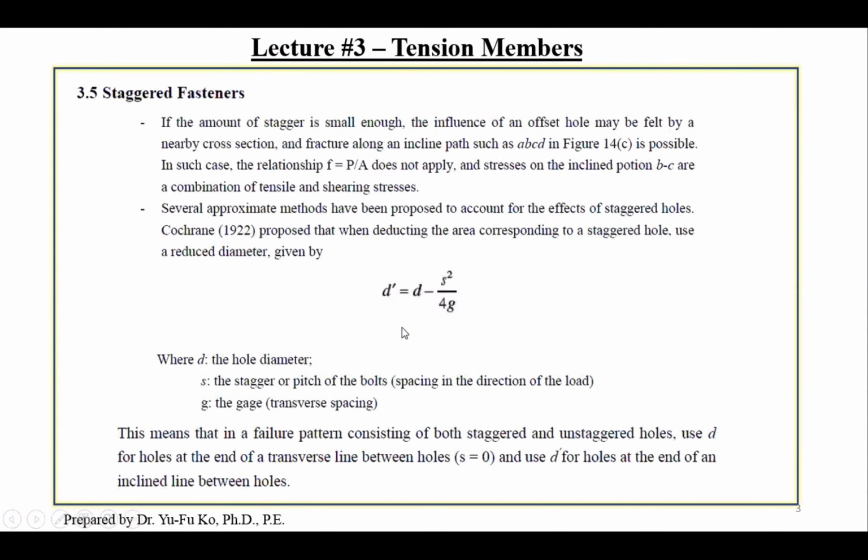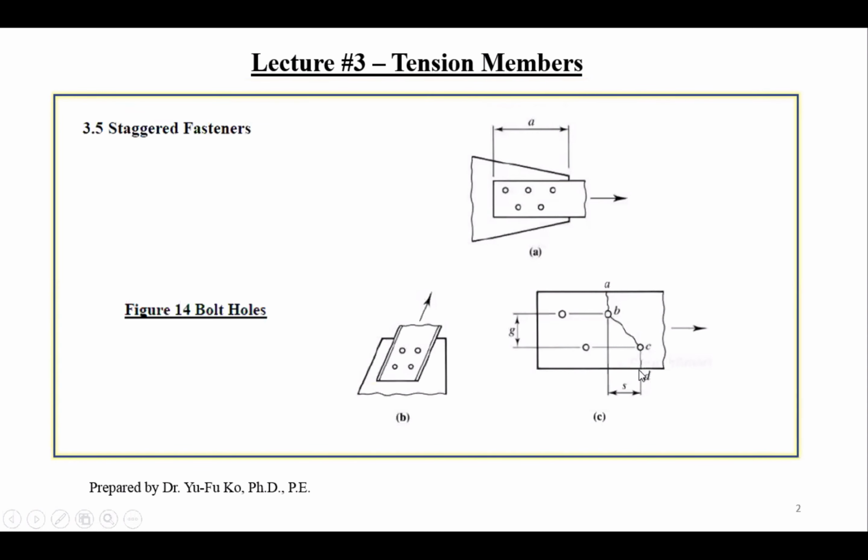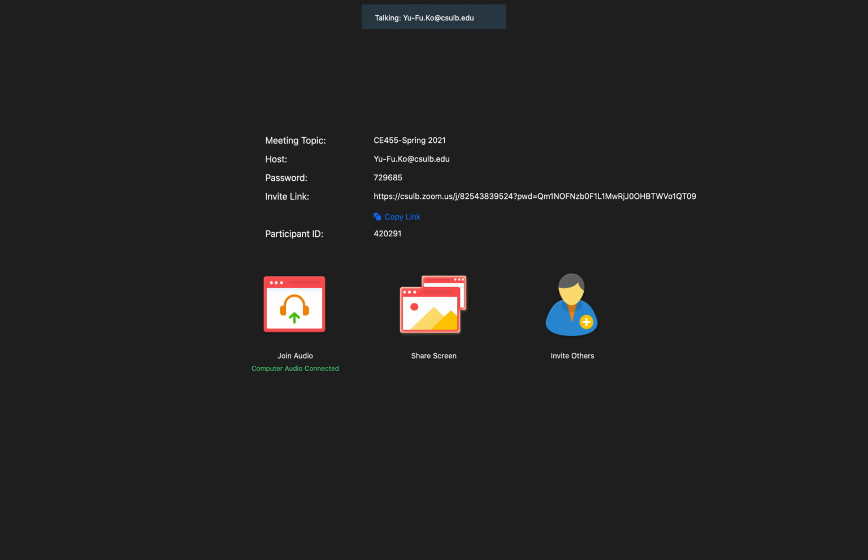Okay. Locally, maybe you see the A net locally maybe stronger, bigger, because the hole value is smaller, right? So maybe you are thinking A net is bigger, but you've got to look at the overall failure path to determine whether it's actually stronger or not, not locally, okay? So we'll discuss on Wednesday, but you guys asked some good questions.